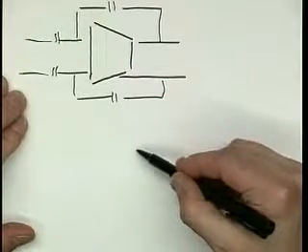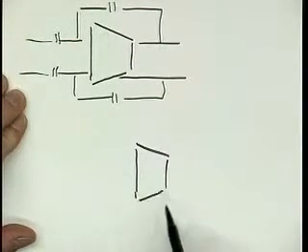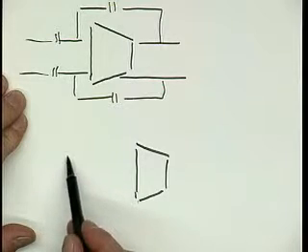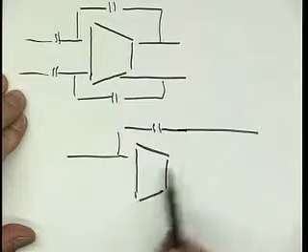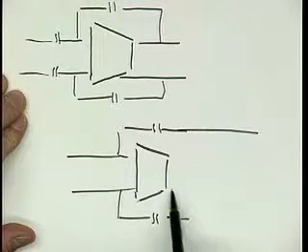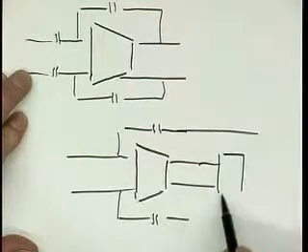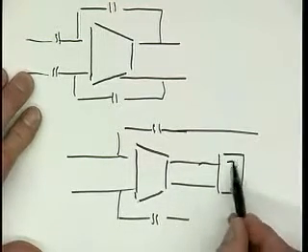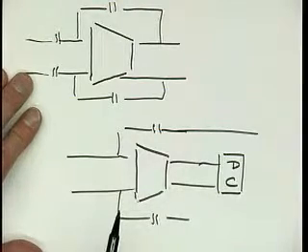And that's easy to do with our balun. So what we would do in this case is we put a balun at the output that transforms the output into a differential and a common mode signal.